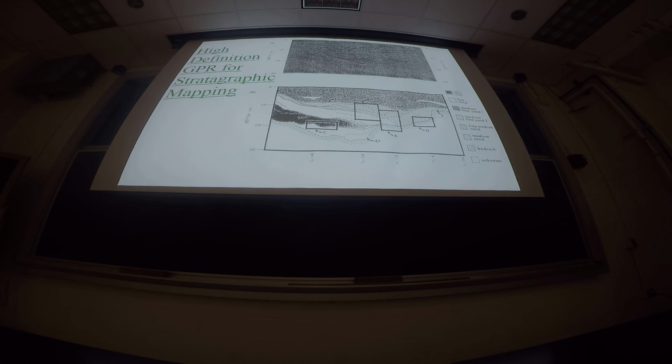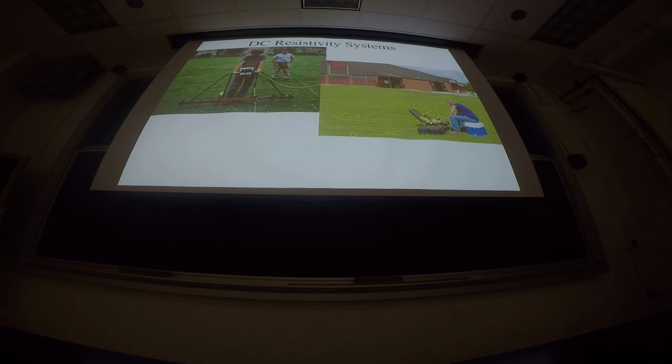Okay, so that's ground penetrating radar. It's kind of like seismics, with a few subtle differences. Unfortunately, it can only be used in the very near surface. Now let's move to other ways of making ground conductivity measurements. As we move below, say, a megahertz, our EM field starts to diffuse, and this is all explained in the handout online if you want to read that. Our EM fields